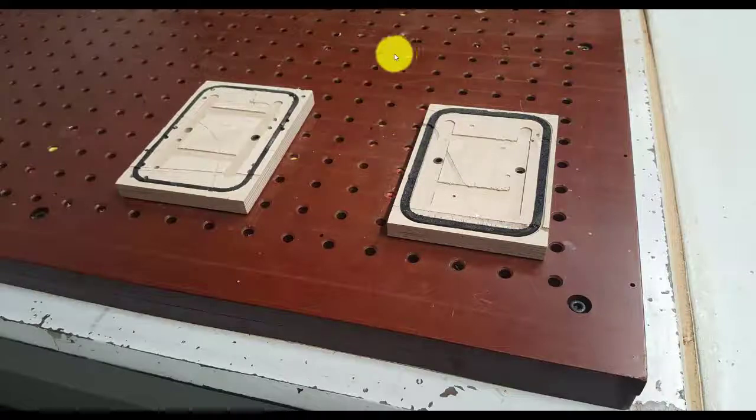Now in this case I don't want to sit this on the bed of the CNC. I want to allow the cutter to go down and cut beneath the surface. So we can use these things. These are ones that are made on site, but these are pods. Now if you look carefully, there are two holes, one there to the right, one there to the left, and there's this little shallow groove. It's kind of in the shape of a cross or an H. And those two little grooves will go down into a hole that has suction going up through it.